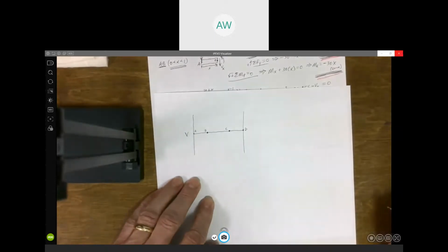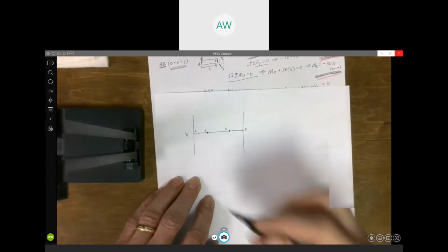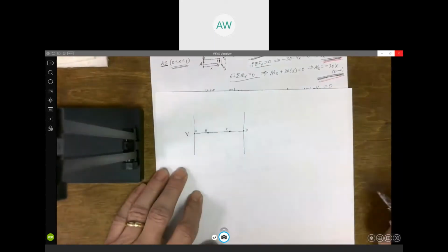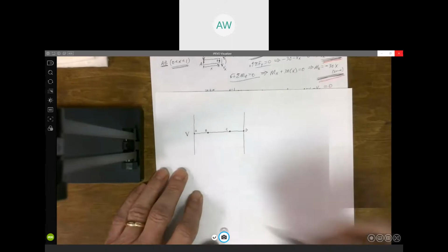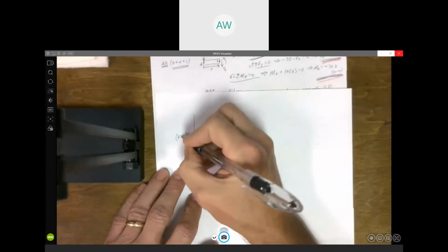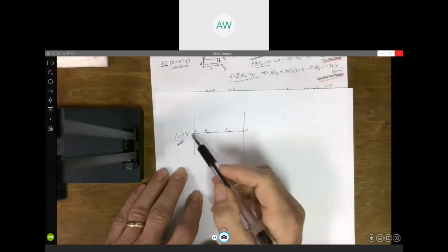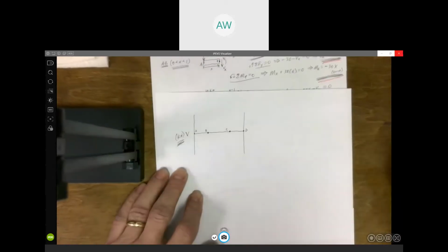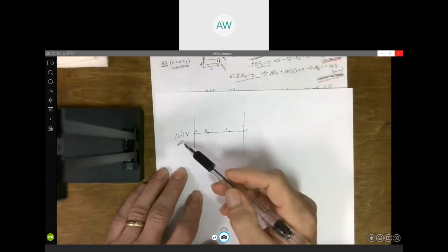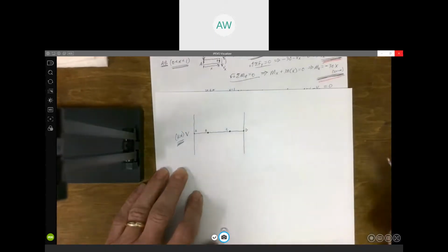So we're going to graph the shear force. And it's important, students all the time leave off units. Now, it's up to you. You don't have to write the units by each number, as you'll see in a minute when we start putting numbers on here. It's sufficient to just put the units once beside V there, and it's understood that all these numbers are in kilonewtons. But if you don't do that, I'm taking points off because you don't put units on there.